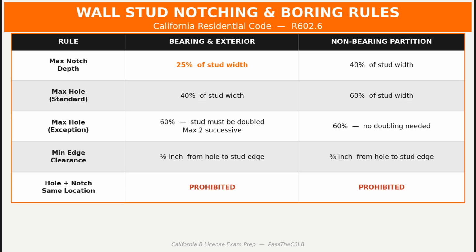California Residential Code R602.8.2 addresses exactly this situation. When cutting, drilling, or notching of the top plate exceeds 50% of its width, a galvanized metal tie must be installed across the cut. The specifications are precise. The tie must be no less than 16 gauge in thickness, approximately 0.054 inches. It must be at least 1 1/2 inches wide. It must be fastened with no fewer than 8 16-penny nails on each side of the opening, and it must extend at least 6 inches past the opening on each side of the cut.